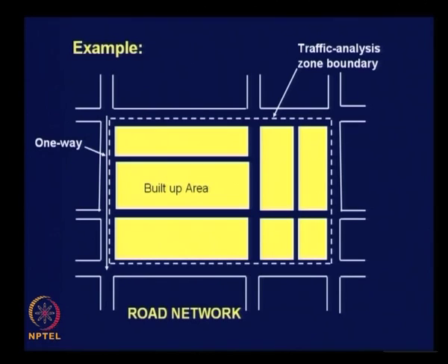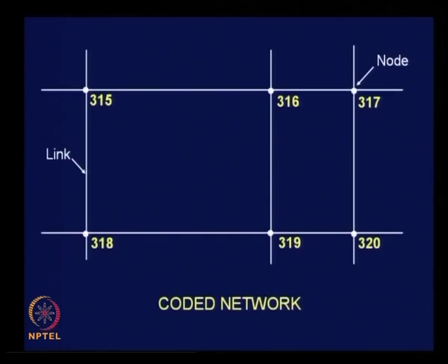And later on we will see how to account for the vehicles making use of these roads as the traffic generated from this particular traffic zone. Clear? So this is how we convert the road network into nodes and links. And what is the designation of this link? How to name this link? Name this link simply as link 315 316. Links are named using node numbers. Okay, use the node numbers to name the links. Clear? That is how we manage.